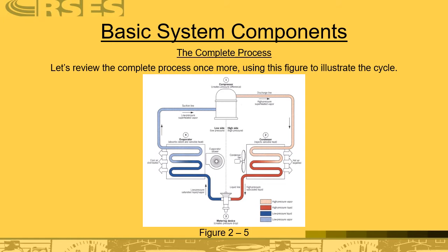And then of course this vapor exits the evaporator coil, goes through the suction line back to the compressor, where this process starts all over again. Please remember, compressors are designed to do what? Only pump vapor, not liquid.